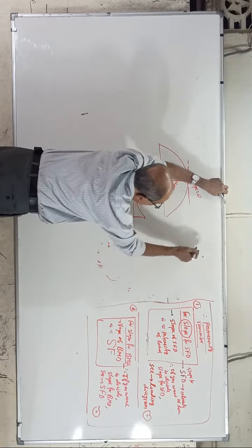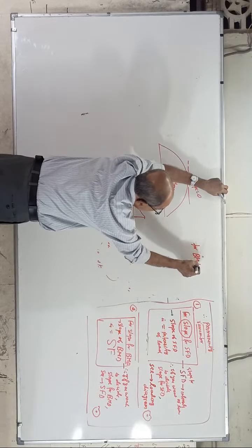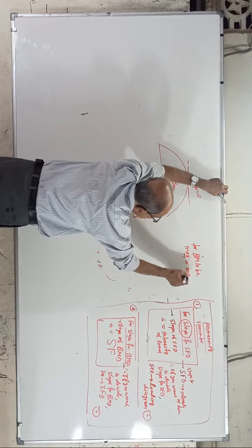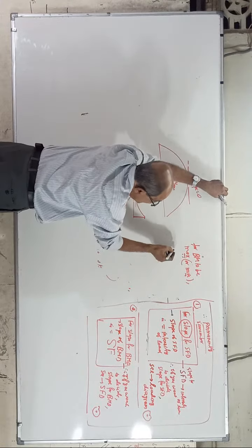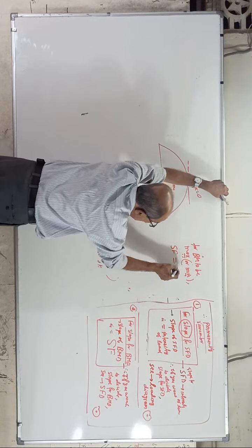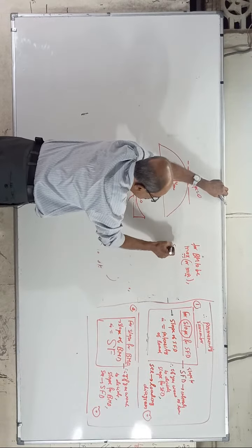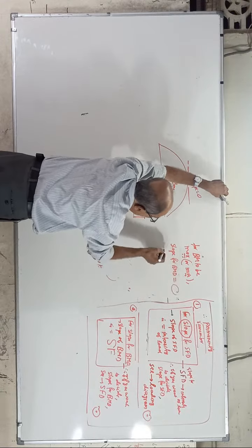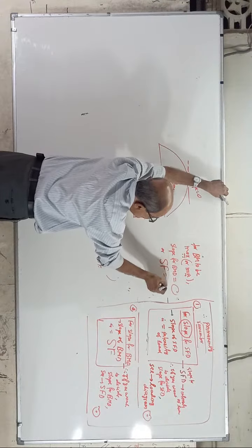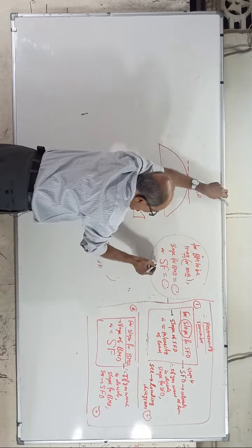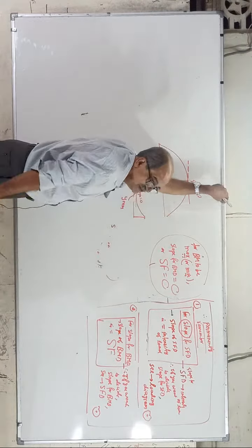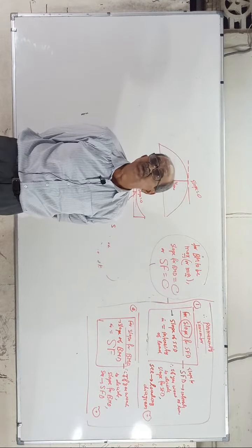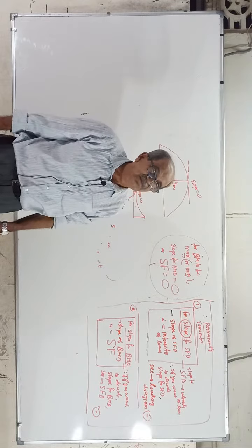One more thing to remember. For BM to be maximum or minimum, rarely minimum, the slope for BMD there should be 0, or you can say shear force there should be 0. But remember, this is not valid for a cantilever. That question I am going to ask on YouTube under a special brain twister. Let the people answer. Beautiful answer is there.